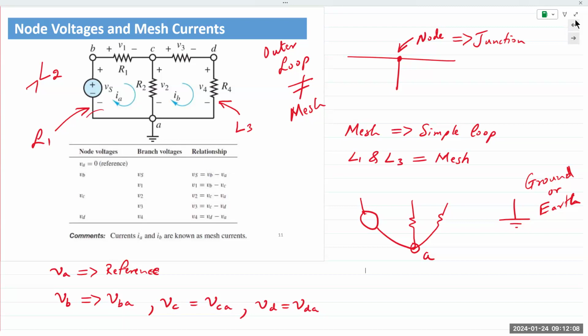All right, so we were here on this slide where I introduced node voltages and talked about the relationship between voltages at every node with regards to a specific reference point. And there's a purpose to this because the first step in node voltage analysis is identifying all the nodes and selecting a reference node. Again, as a reminder, voltage is always measured between 2 points. It is the difference in electric potential between 2 points. So we need a reference for measurement, a baseline for measurement. In this example, it's the bottom node.